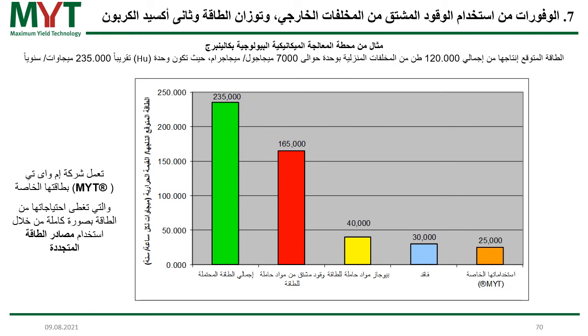This is, to me, one of the most important slides, and I would like to explain it to you. This green column shows you the energy potential which is delivered to your waste acceptance hall over the year. So it's 235,000 megawatt hours per year. This is the energy potential delivered to your facility when we estimate about 7 megajoule per kilogram as the calorific value of the waste, and about 120,000 tons of waste. So this is the energy potential.